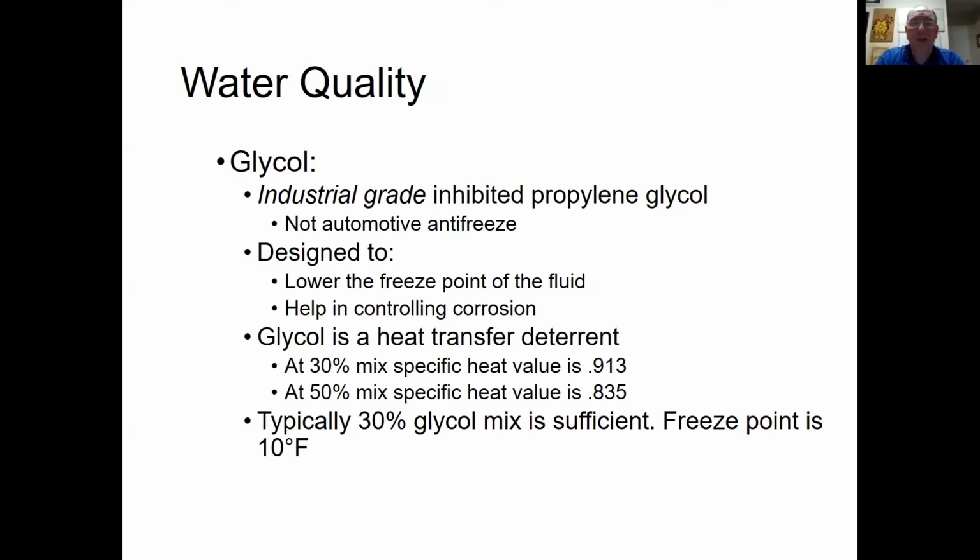But if you use a glycol, you need to use an industrial grade inhibited propylene glycol. Do not use automotive antifreeze. Automotive antifreeze is designed for closed systems, in other words, not exposed to atmosphere, and they have silicates in them that, if exposed to the atmosphere over time, start to plate out. And again, you'll get that jelly mess that I mentioned if you were to run glycol in a tower.